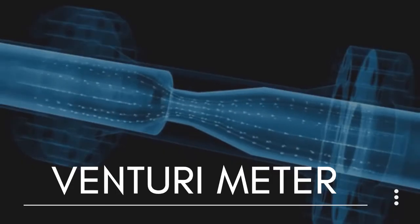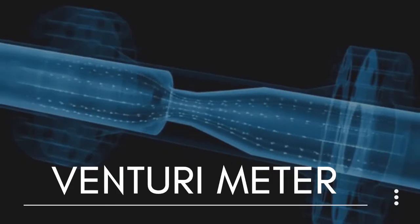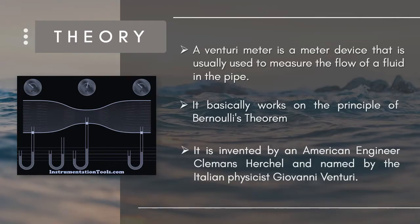Next is the Venturi meter. A Venturi meter, also known as a differential pressure flow meter, is a device that is usually used to measure the flow of a fluid in a pipe. It can also be used at any specific point to increase the velocity of any form of fluid in a pipe. It functions practically on the principle of Bernoulli's theorem, which states that a region of fast-flowing fluid exerts lower pressure on its surroundings than a region of slow-flowing fluid.